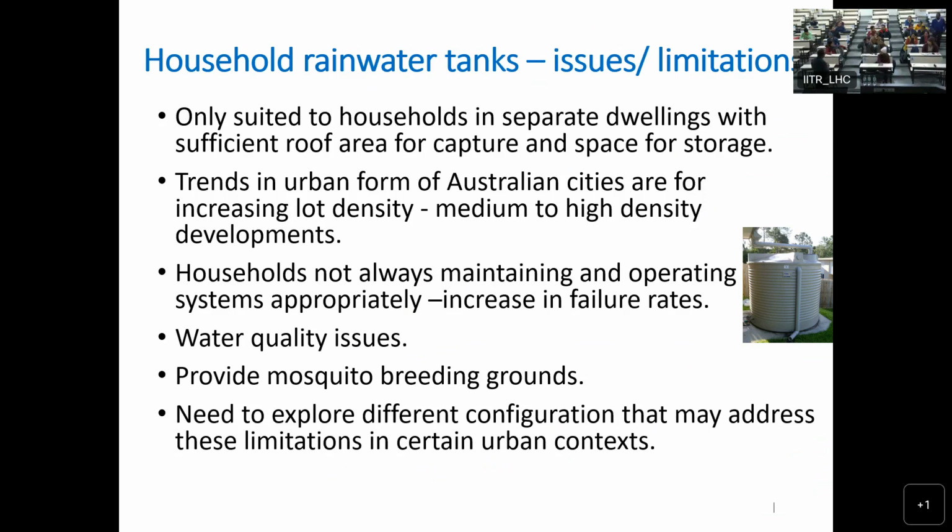I have a doubt also. When designing an overhead sump, for the capacity we plot the supply curve and demand curve, and we see the maximum difference between the two, cumulating on the addition, and we say that this is the capacity. Can you adopt the same approach here also?